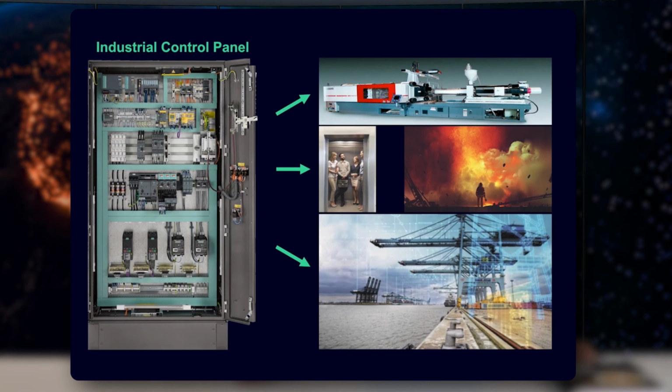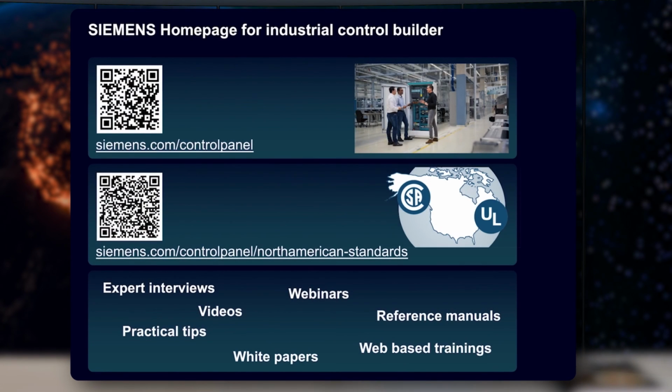Furthermore, industrial control panels mainly contain numeric controllers like PLCs, CNCs or industrial computers for controlling all different loads. You can often find in an industrial control panel a busbar system to bring the electrical power to converters, to control and to monitor electrical equipment, including overcurrent protection and all associated control circuits. The safety standard which covers the requirements for designing all these individual industrial control panels is the UL 508A. Now we come to the end of this tutorial.